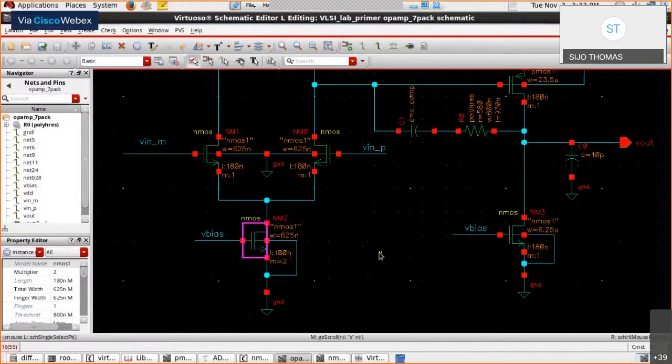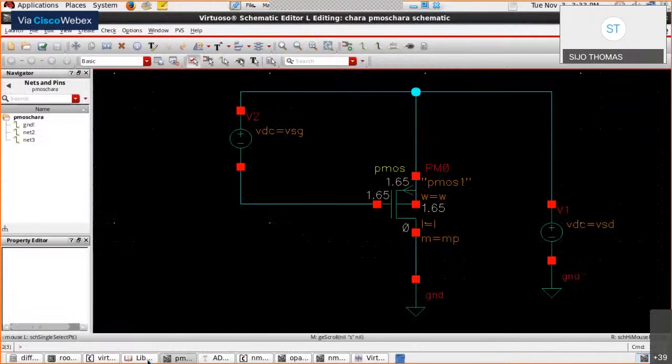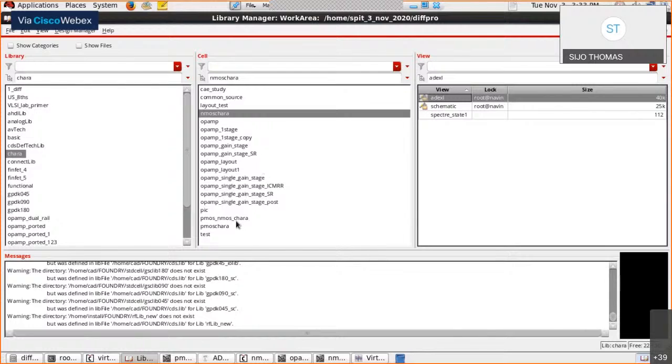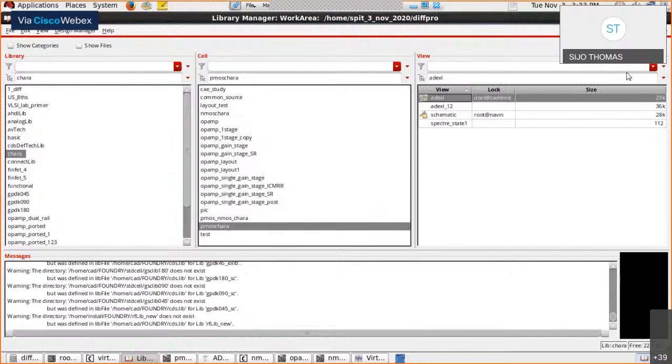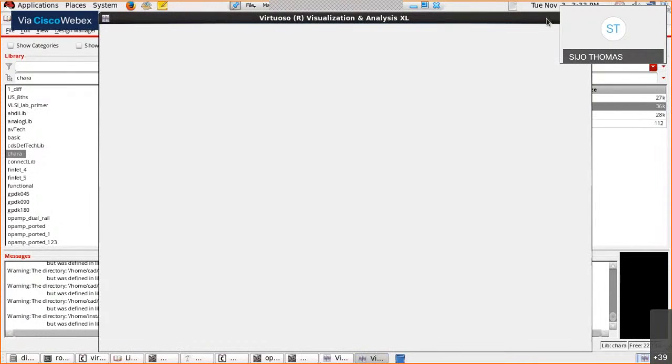Now we look at the curves for PMOS and we will set up the W value for PMOS also. Again you can do the same exercise. We have to plot the current density across gm/ID. So gm/ID remains the same.